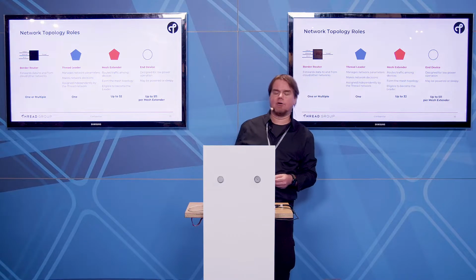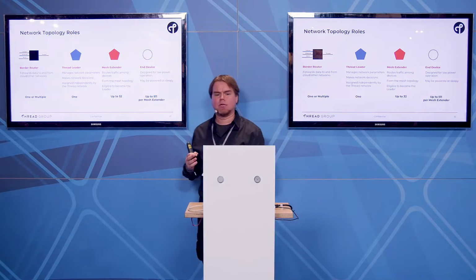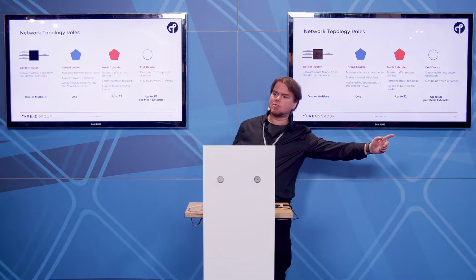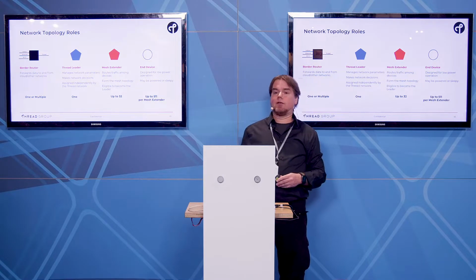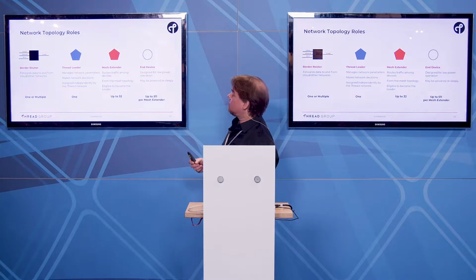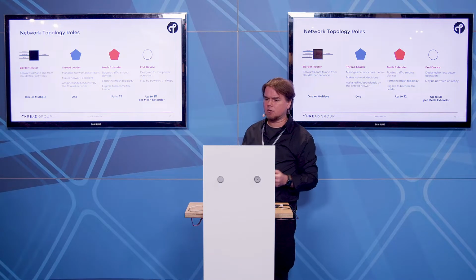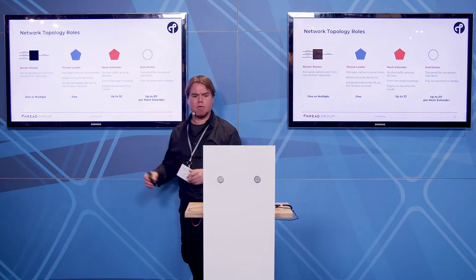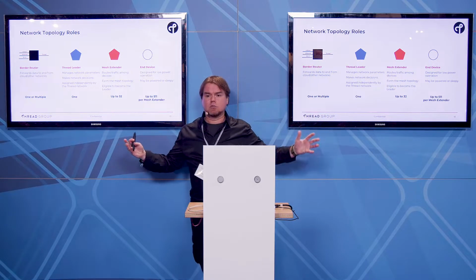All mains-powered devices on a Thread network are what we call mesh extender devices. So a light bulb that's connected to mains power can perform that mesh role. It receives packets and transmits them further to the other devices. And end devices are battery-operated devices, and that's enabled by the fact that Thread is based on a low-power technology. Battery-operated devices are in a sleepy mode until they are woken up by one of the other nodes on the network. And the battery-operated devices can last for many years, multiple years on one battery, which is of course important in buildings where you might have hundreds or even thousands of sensors.